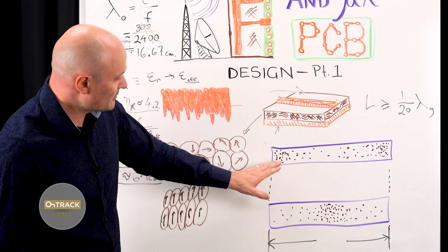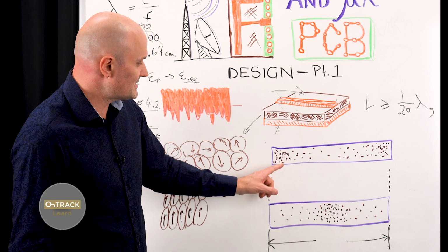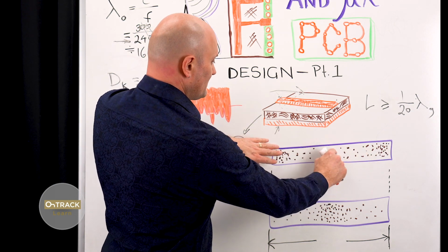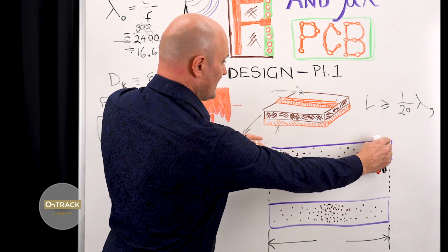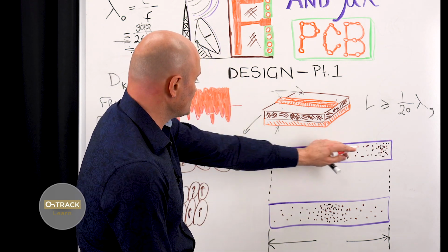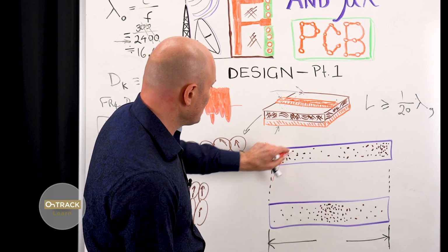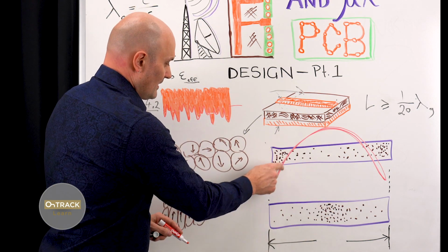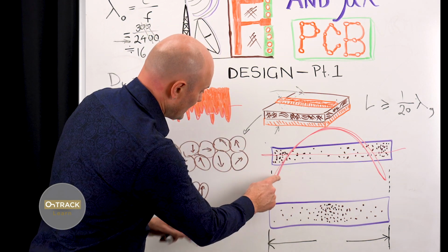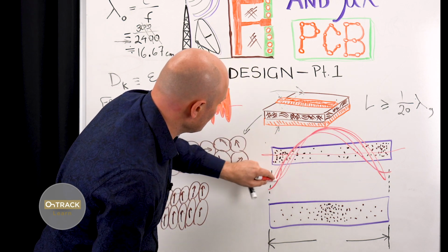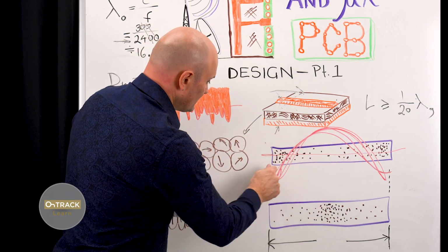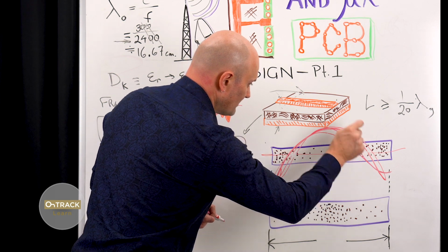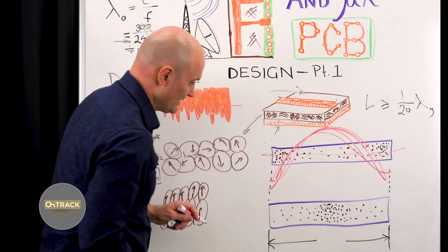So in any conductor, we can place a voltage source and have the electrons at one time instant all go away from the middle. So we have a net positive charge in the middle of the conductor and negative at the extremities. If we could graph the voltage over the distance of this conductor, we'd see this kind of waveform. This would be a positive half wave of a sine wave on this conductor, just phase shifted. We have negative at the extremities, positive in the middle, and net zero charge a quarter of a wavelength in from each end.